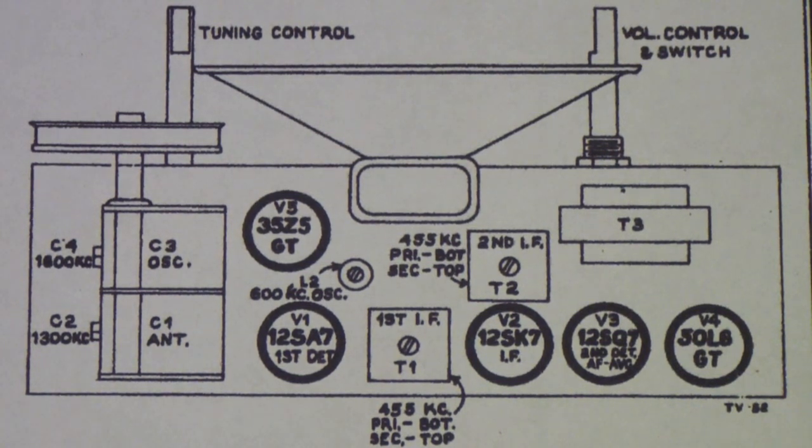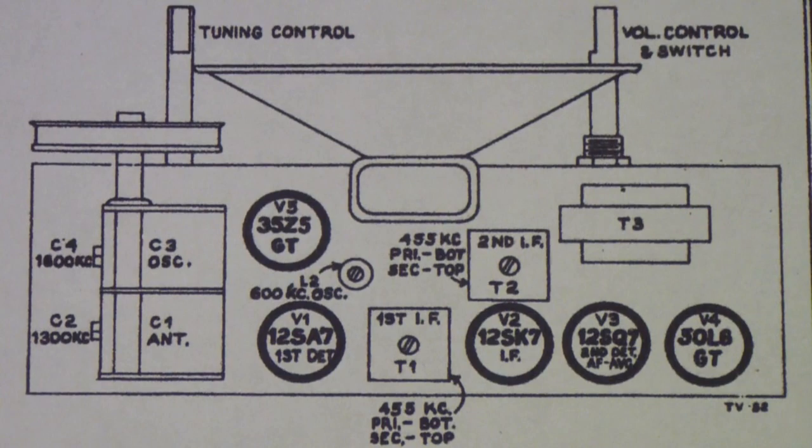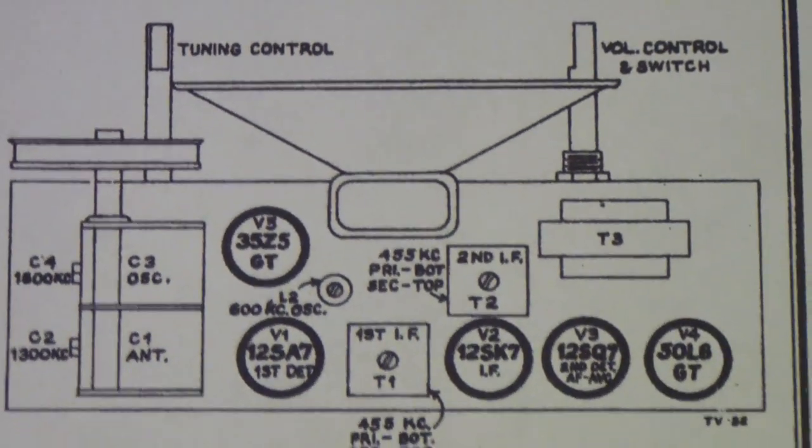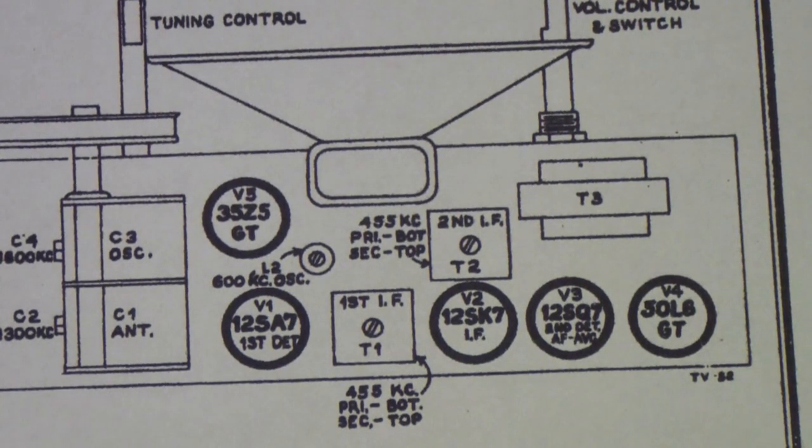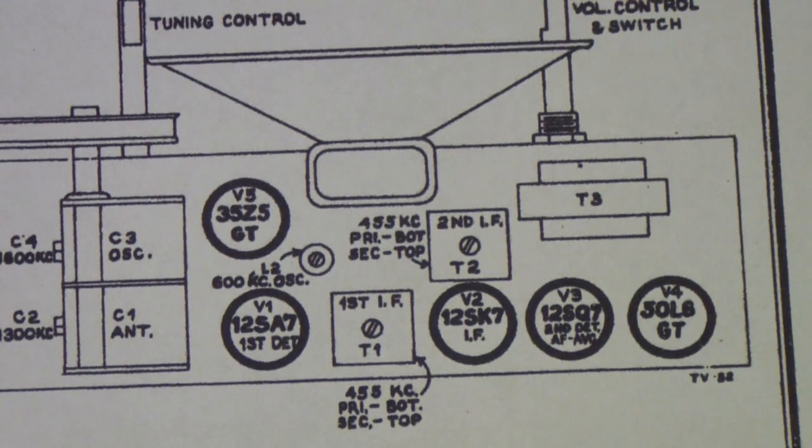Now, if you're doing an FM stereo, that's a different issue. If you're doing a shortwave radio, that's a different issue also. But for most All-American 5 AM radios, I recommend, as I said before, if it works, just leave the alignment as it is, unless you really want to spend the money and go through the exercise.